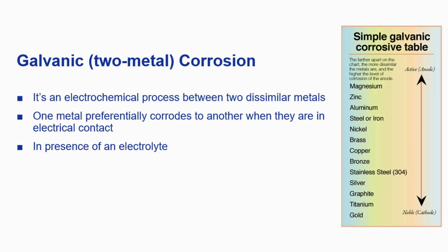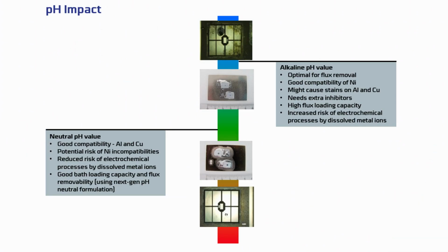In such cases, especially power electronics, it's really important to use the right chemical and the right cleaning equipment, because the chemistries need to have good corrosion inhibitors in their formulation, which will avoid any galvanic corrosion related failures. The failure mechanisms that we come across with this type of components are electrochemical migration and corrosion-induced leakage currents. And in the case of semiconductor electronics, we have to look at the bond strength, the shear strength, and such factors.